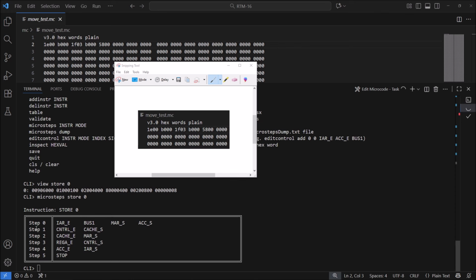So it means that whenever we come down to this set of instructions, if you'll note, we've got instruction address register enabled. Now the way our fetch execute cycle works, if you remember, is that once it's fetched them, it adds one on to the instruction address register. So the instruction address register doesn't contain the address of the instruction you're running now. It points to the next address. So it's actually pointing to this address here. I don't mean it's pointing to B000, it's pointing to the 0x8001.